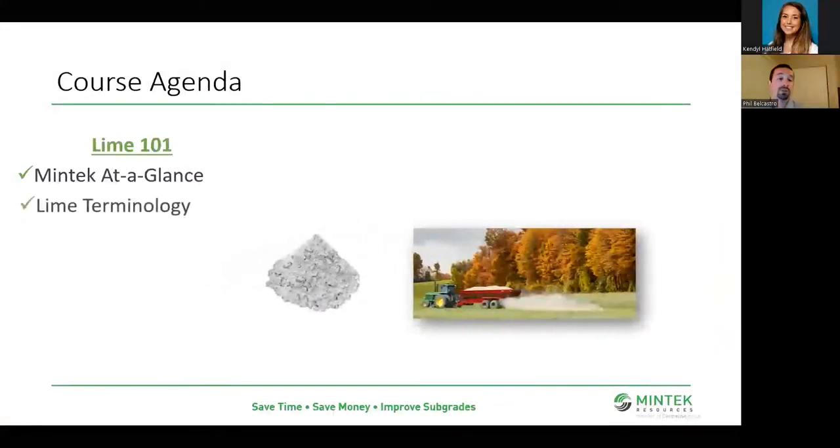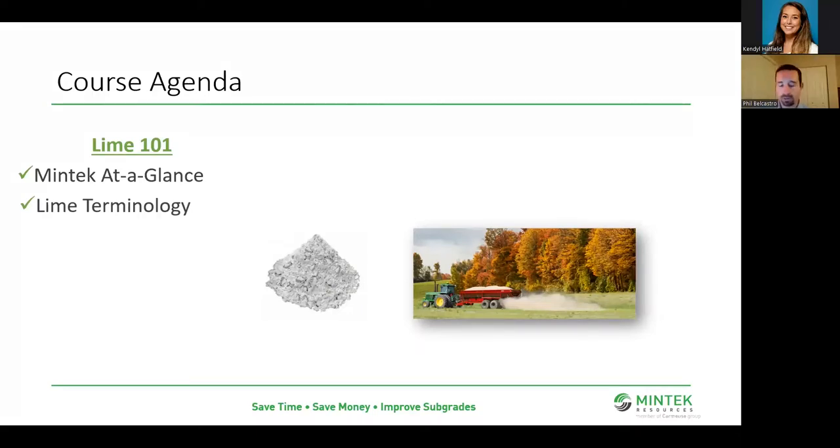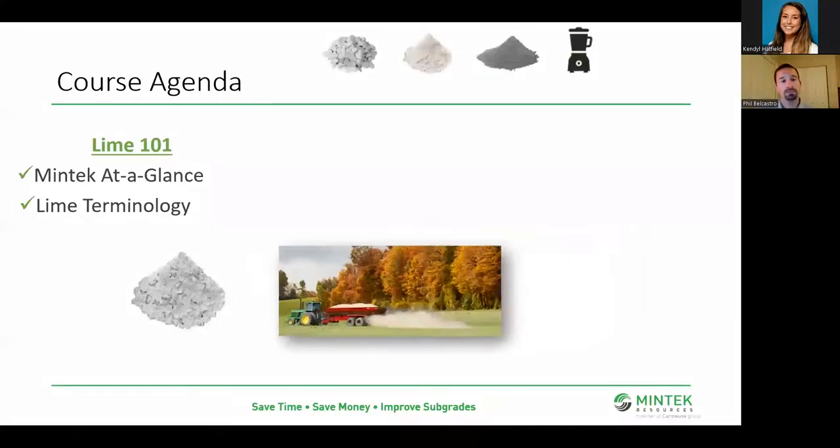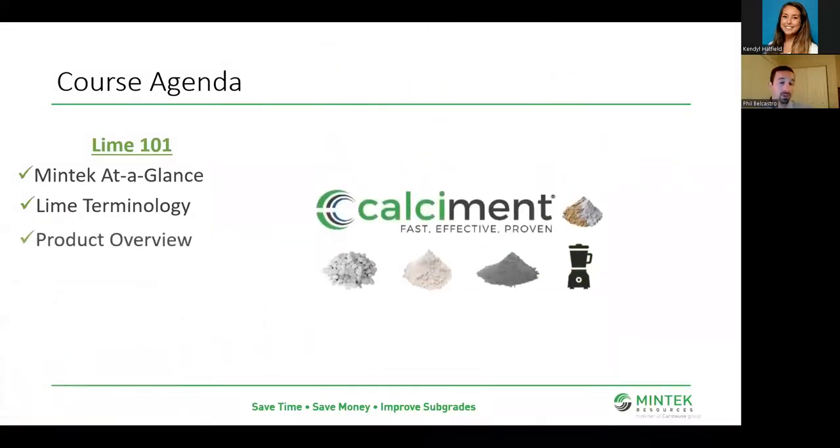We of course looked at lime terminology. What is lime? Don't be afraid to ask someone who's saying that they're using lime, what are you doing? Is it quicklime, hydrated lime? Is it ag lime? The difference between all three, and of course we're not talking about the fruit. The products we went through, we've got our Calciment LKD, a nice gap between Portland cement and quicklime. And we have quicklime, hydrated lime, some Portland cement capabilities along with blending capabilities as well.